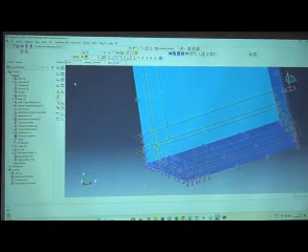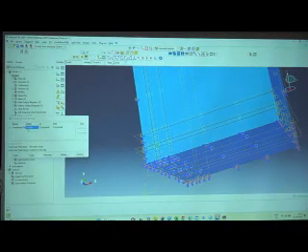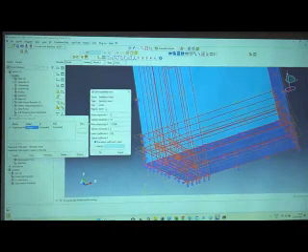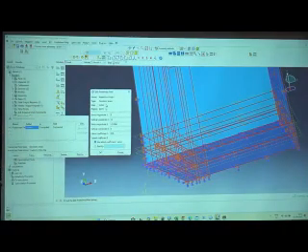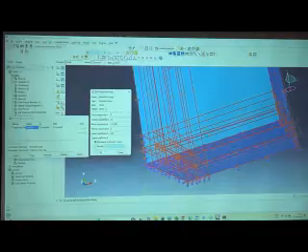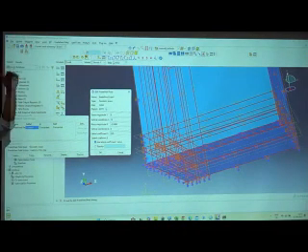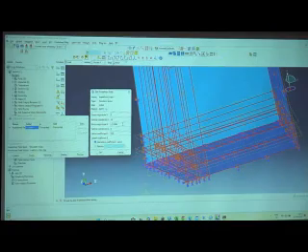After this, the first step is to apply the geostatic stress. So how did I apply the geostatic stress? Geostatic stress means at the initial step you have to apply the geostatic stress. As I already told, first geostatic stress should be applied, then gravity, then the load. The magnitude of stress is 0 at the top, and at the bottom it is minus 211,896.